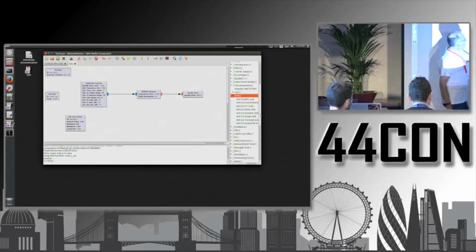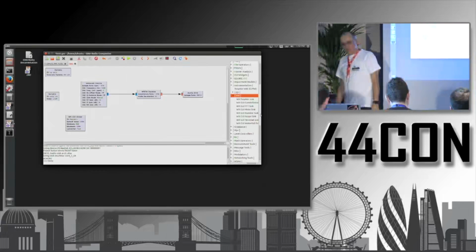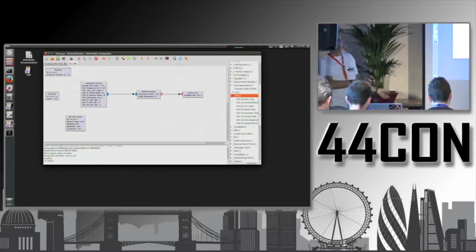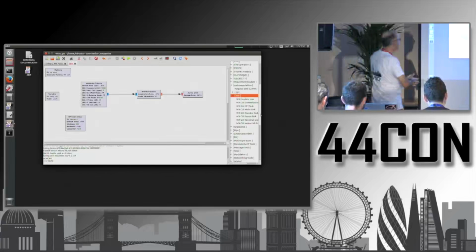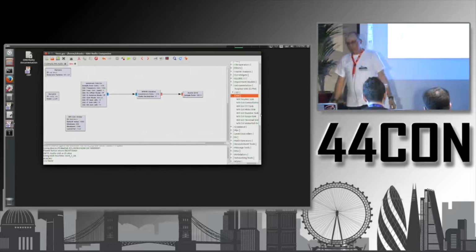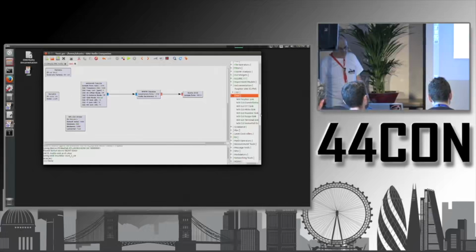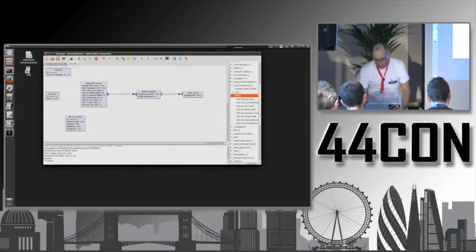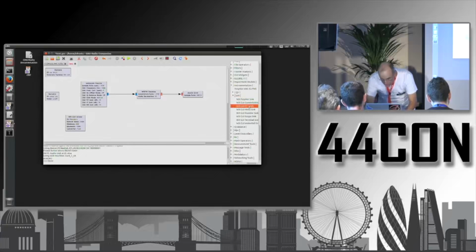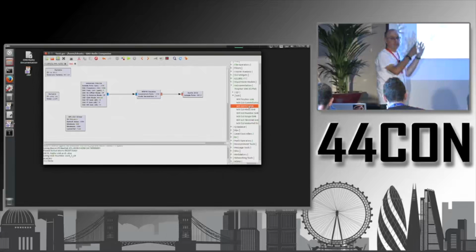So if you go to instrumentation, you have, again, QT and WX. We will use WX. In instrumentation, you can add instruments to your radio and observe what is happening inside. And now you will see the power of this GNU radio environment and software-defined radio. For example, we'll use a fast Fourier transform sink so that we can see the visualization of the frequencies.